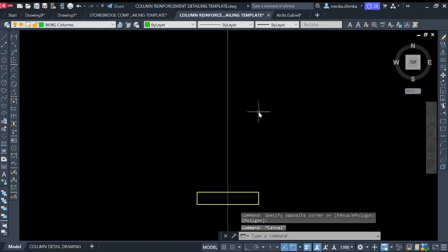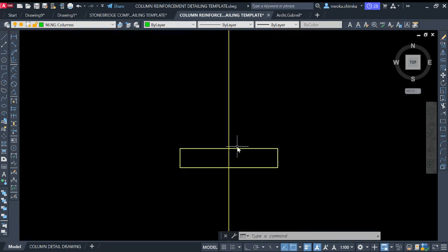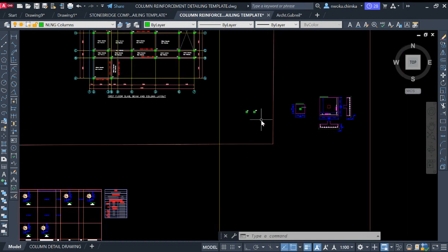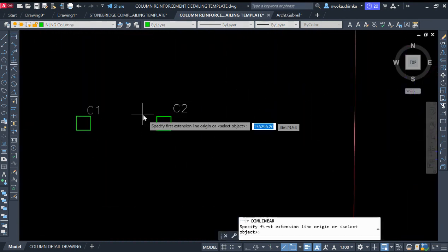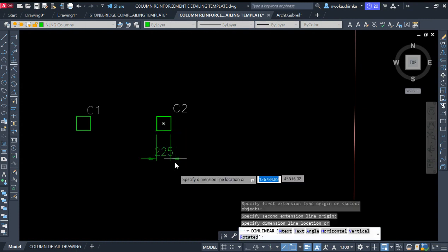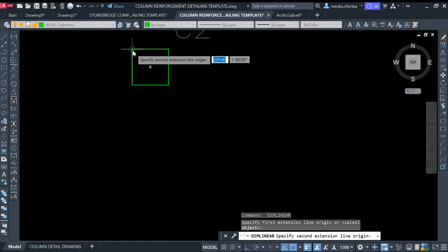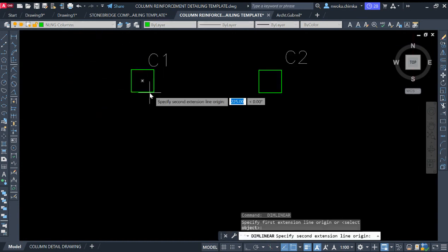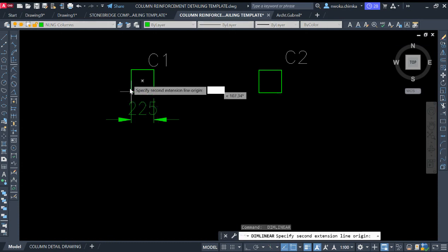Okay, so again, what I'll do next is to now offset, since I've gotten my base, my base footing. Next thing to offset is this column size. You can see that this column size is 225 by 225. Let me just check it out. This is the size of the footing of the column, as you can see it here, both the length and the width. So this is a square column, as you can see it here. The same thing happens to this place. Square column, as you can see them here, and also this.